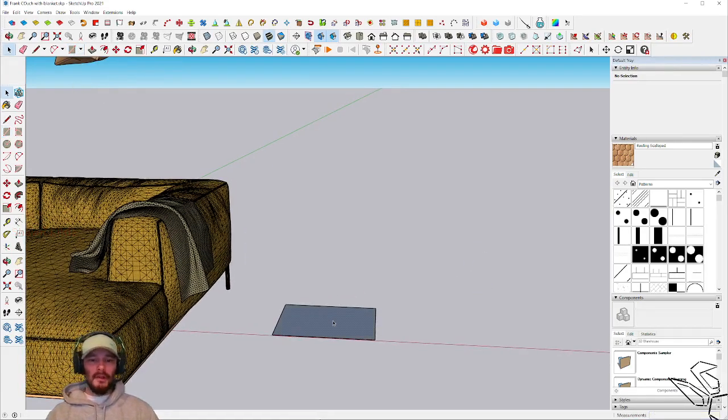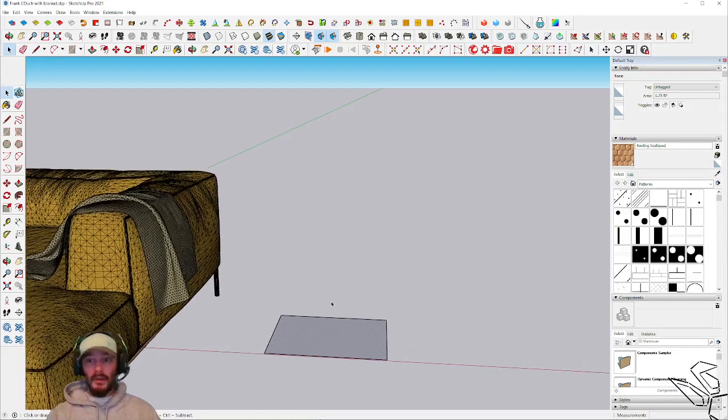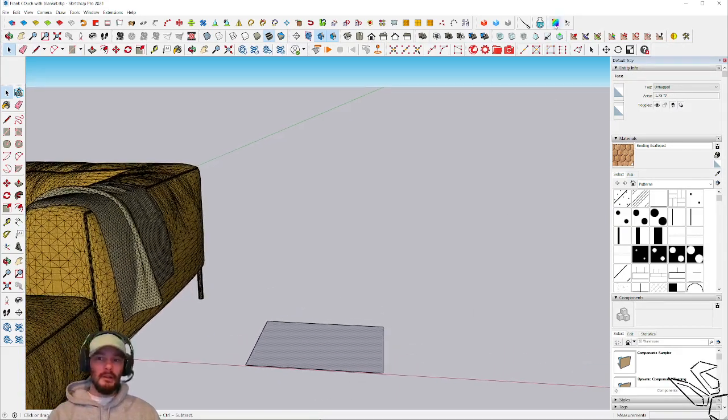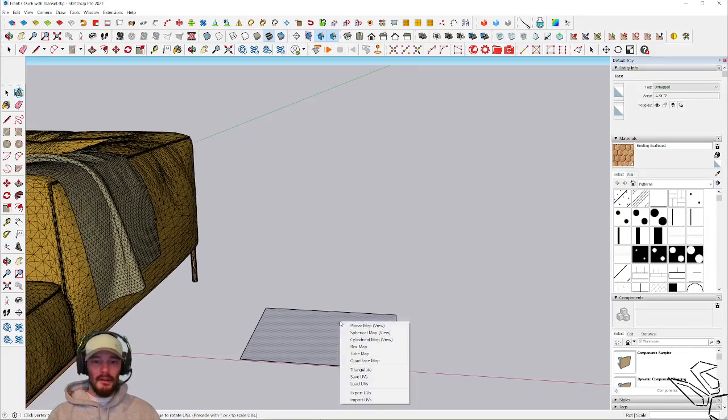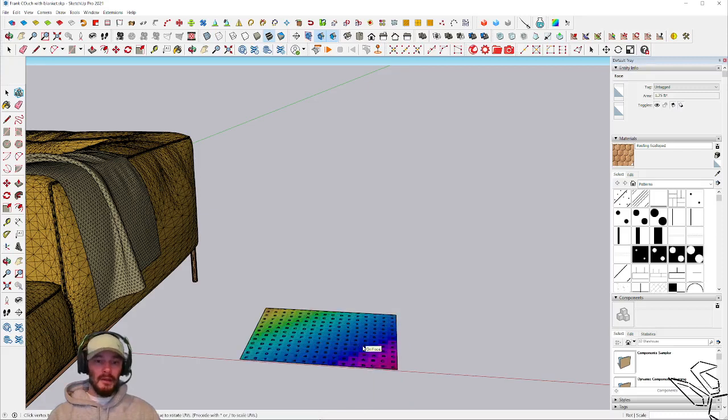And then I'm going to reverse this face. Simple enough. Now, before I just make this into a pillow, which I could quite easily, I'm going to use a plugin called Sketch UV. What Sketch UV does is apply a UV map to this. As I'm creating the pillow, it's going to stretch geometry, so applying materials to stretched geometry is not going to look good. So before I do that, I want to ensure that I have a texture already mapped to this, the way I like it to be mapped.